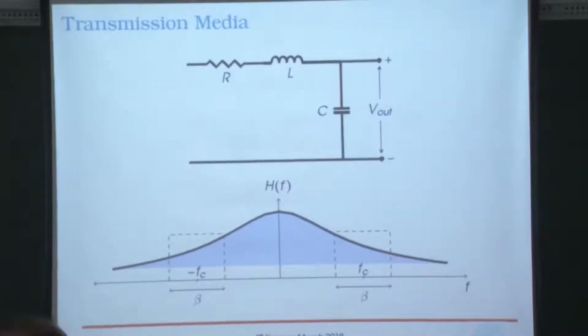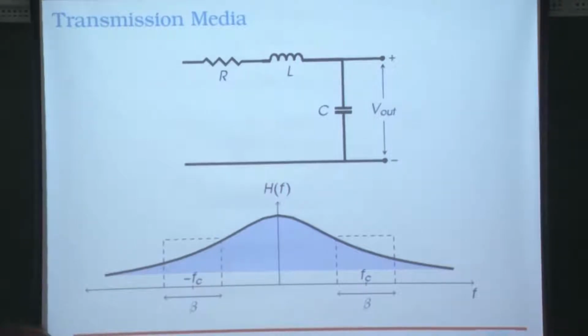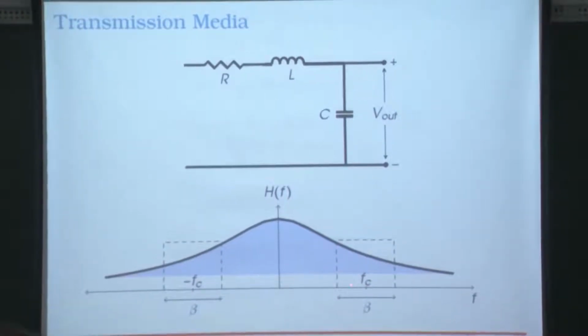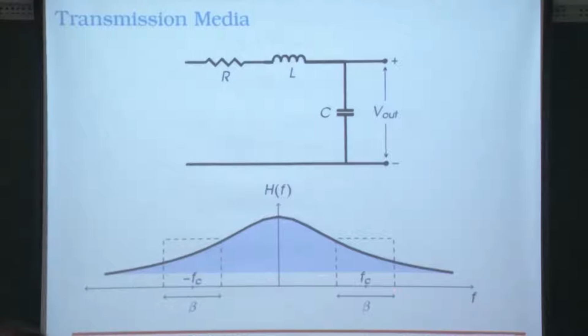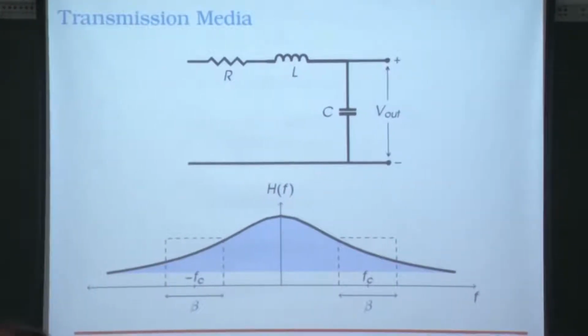So why is it symmetric? Yeah, so of course we are trying to push real energy into an antenna out there, pushing the real vibrations of the electromagnetic field. So we are talking about a real system. That's why I drew the magnitude as symmetric with respect to frequency. Now if you use a bandwidth beta here, then I can generate a waveform which has bandwidth beta, multiply it by a carrier, and send it through this particular part of the spectrum.